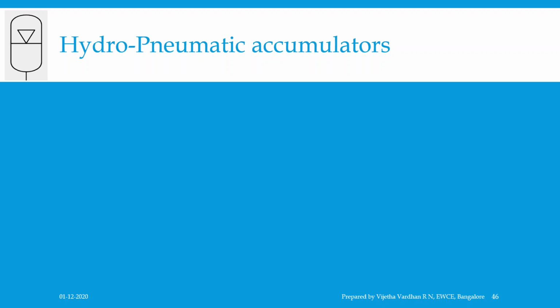fatigue. Then coming to the third type, called hydropneumatic accumulators, you can see the graphical representation in the figure, called the gas charged accumulator. The most commonly used accumulators in industries are of the hydropneumatic type. In this type, the force is applied to the oil using compressed gas. This works on the principle of Boyle's law of gases, which states that at constant temperature, the pressure of the gas varies inversely with its volume. The compressibility of gases is responsible for the storage of potential energy.